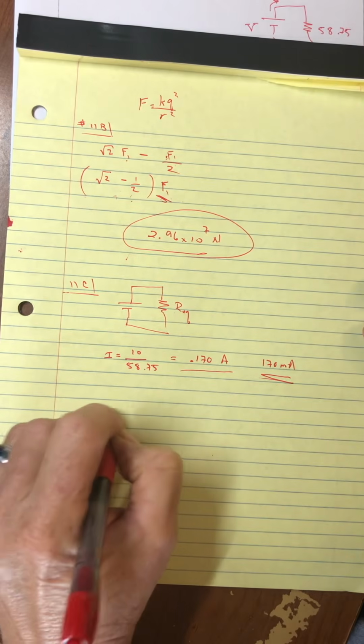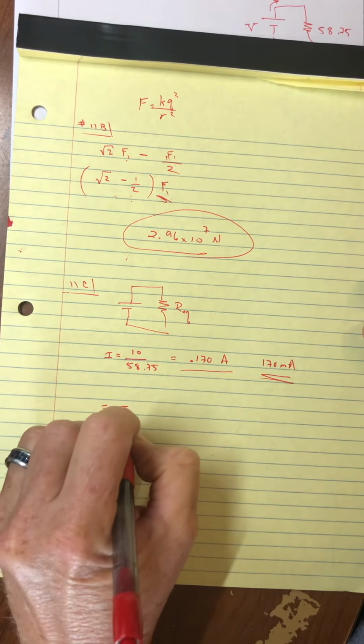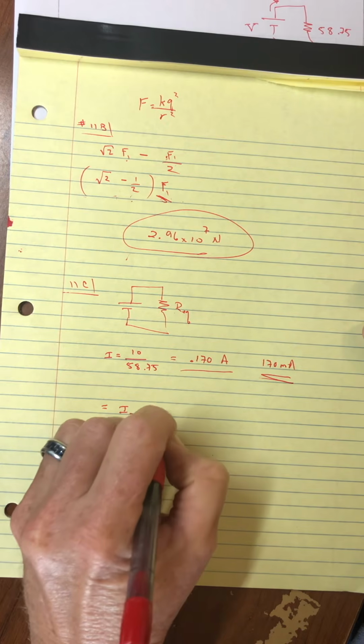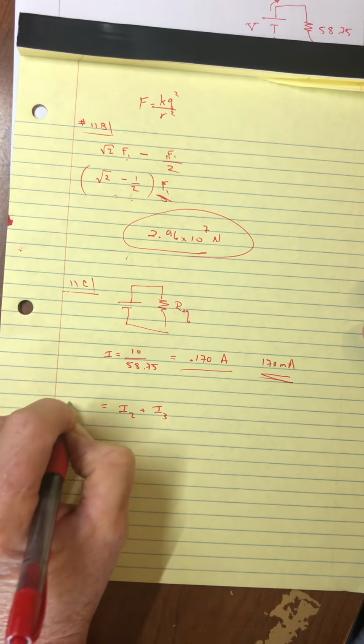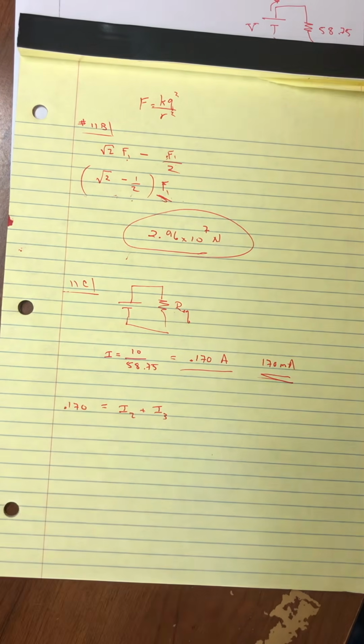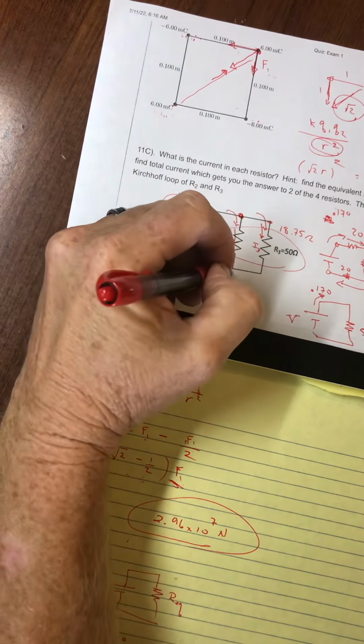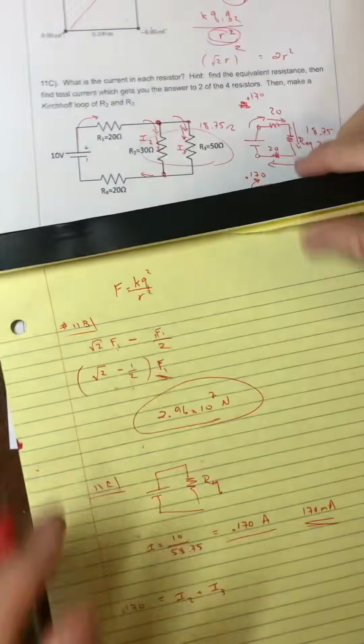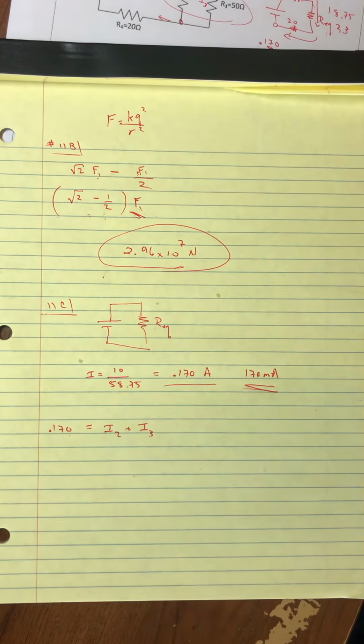And so one of the pieces we know is that current number 2 and current number 3 must add up to our total current coming out of the battery, which goes through that first resistor. It also recombines after the resistors 2 and 3 in parallel. So either way you want to look at it, either of those 2 nodes, this top node or this bottom node, the sum of the 2 currents is the total, which we already have.